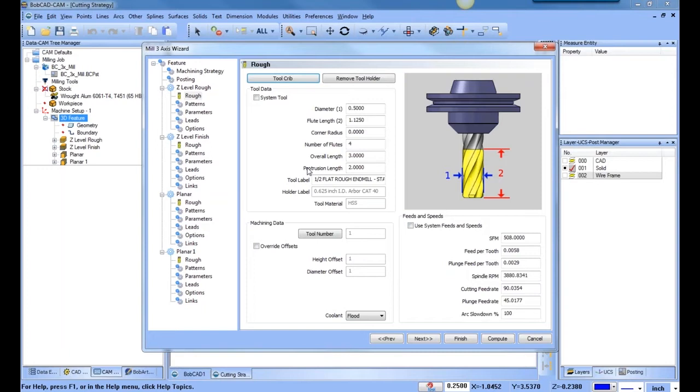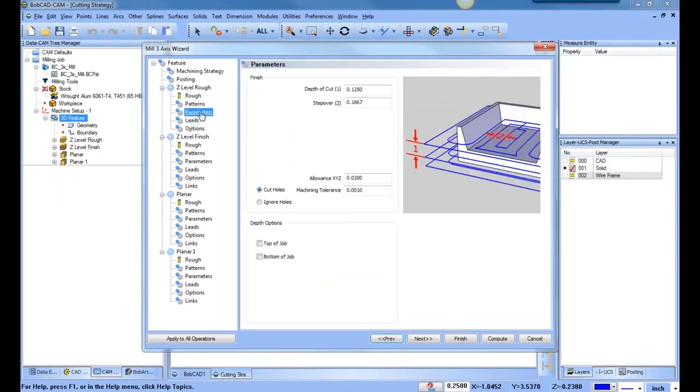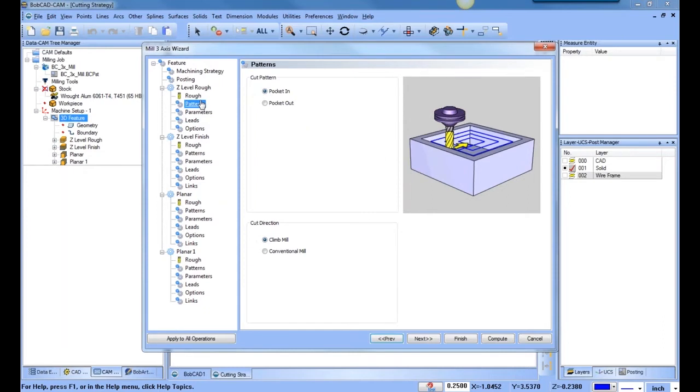Now there are some strategies that you want to use with your tool crib, loading a tool crib and calling tools from a tool crib when you're dealing with tool numbering. There's also with save and load for different cycles, like drilling cycles. There are some different variances as far as what's saved and what you will load. So when you're dealing with just specifically these three strategies here, your tooling information, if you uncheck system tool, that should come over right away, but I would really want to talk about using a tool crib and loading that tool crib prior to loading a feature in that uses a tool number. Okay, speeds and feeds, if you uncheck use system speeds and feeds, these are going to come across, and all of the other settings, when you save that feature or copy and paste them, they're all going to be defaulted. So those are going to be the settings that are going to be used there.